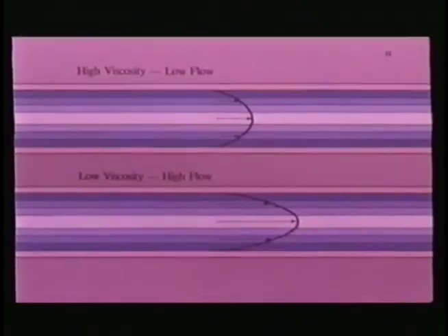22. For a given pressure difference, the volumetric flow rate is lower for a fluid with high viscosity than for a fluid with low viscosity. 23. Viscous resistance also varies directly with the length of the tube. For a given flow rate, fluid viscosity, and tube radius, the longer the tube, the greater are the resistance and pressure drop.